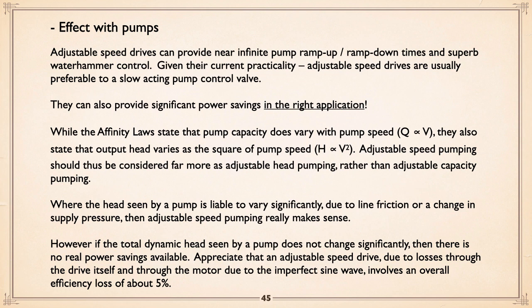Now, this is a big point. I've seen ads where they say, well, you're going to put on a variable speed drive and it's going to save all sorts of energy. Isn't that wonderful? Every time you use a drive, variable speed drive or adjustable speed drive, you're saving power. In some applications, in the right applications, they can be quite significant. But there are applications where it will cost you power.